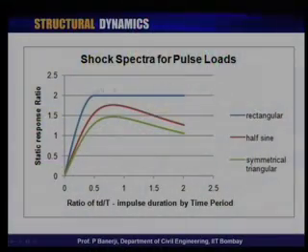So, that is what is known as pulse load. I have shown you that in pulse load, short duration loads, you do not only have one solution like we used to have for harmonic and periodic loads; you have a phase 1 solution and a phase 2 solution, and I also showed you how to compute the peak. For the rectangular, we knew exactly when it will occur in phase 1 and when in phase 2. For the half sine, for phase 2 you can get a closed form solution, but for phase 1 it is not a closed form solution for the peak value, so you do not know where it is.